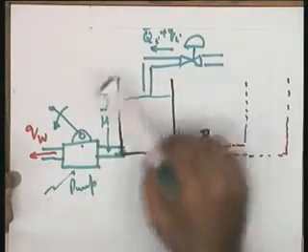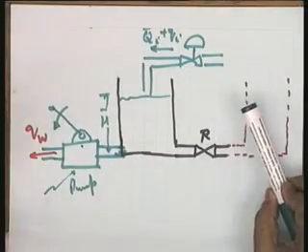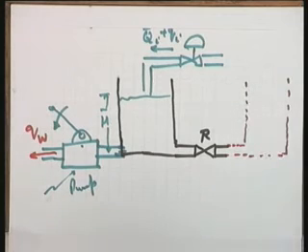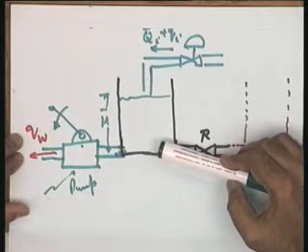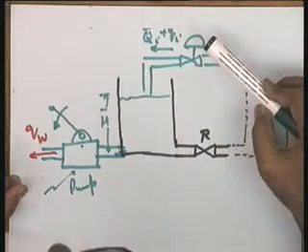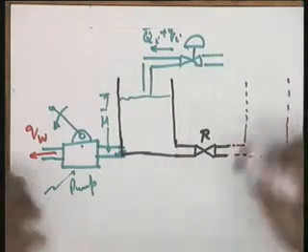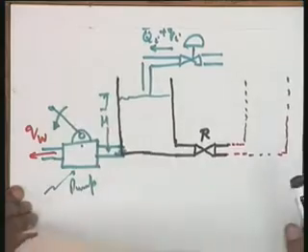But as far as the mathematical model is concerned, or as far as the setting of the control system is concerned, I think there is no problem in that, because I am making a setting, a regulator setting, in which the control action is to bring the height of the liquid to the preset height, because this particular tank requires that. I hope you have got this point. So taking this QW as a disturbance, now you have to help me, please give me the mathematical model for this now.